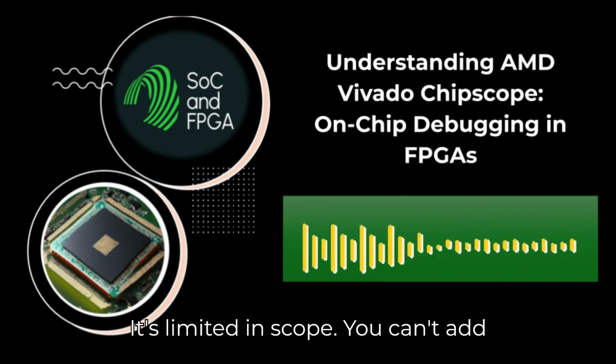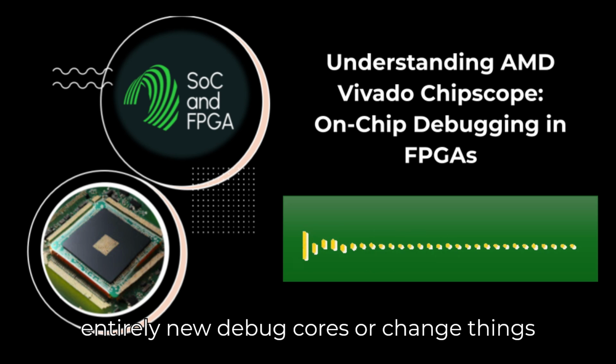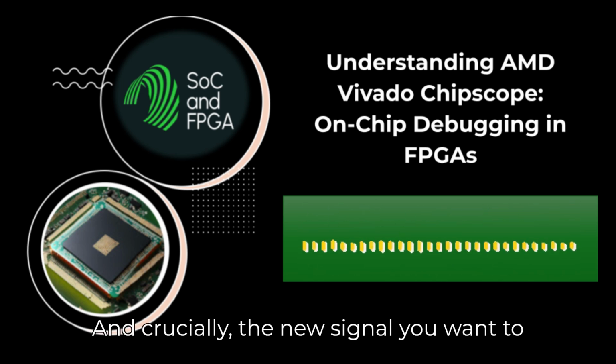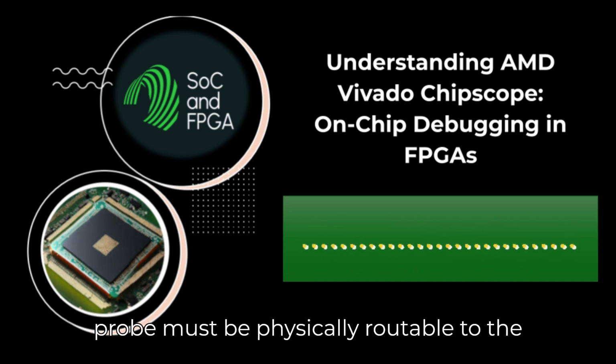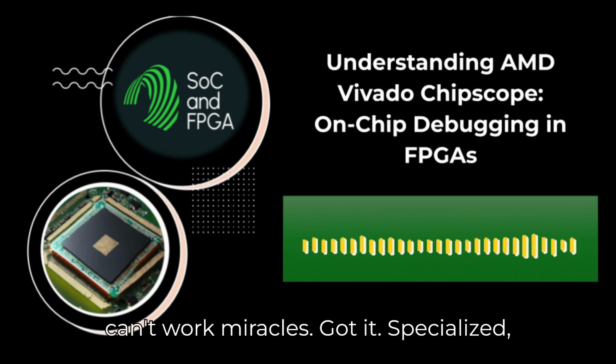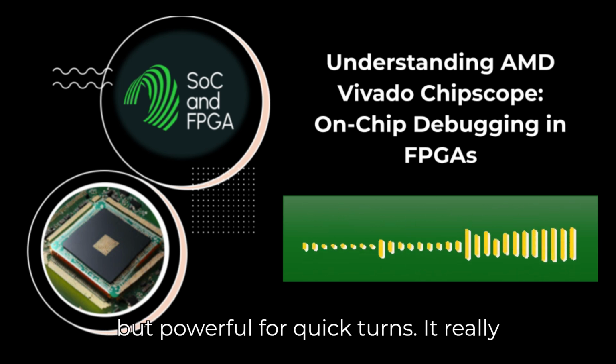What's the catch? It's limited in scope. You can't add entirely new debug cores or change things like the data depth of an existing ILA. And crucially, the new signal you want to probe must be physically routable to the existing ILA's location on the chip. It can't work miracles. Got it. Specialized but powerful for quick turns.